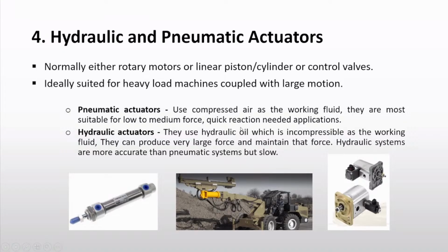But not like the pneumatic actuators, which are quick reaction, that means they give a fast response, the hydraulic actuators are more accurate but very slow. So normally these hydraulic actuators are used in heavy machinery and the equipment that we can see in construction fields.